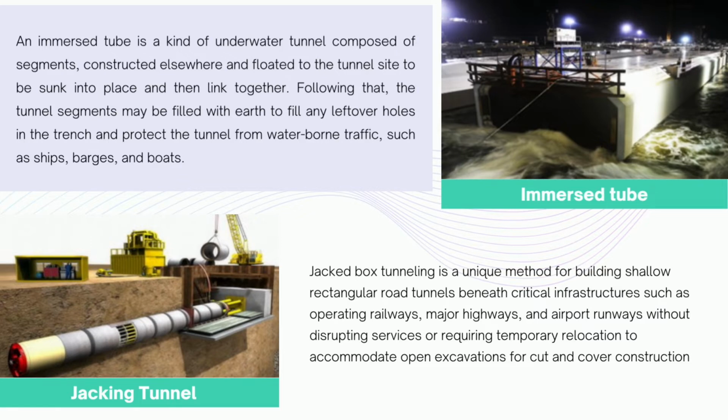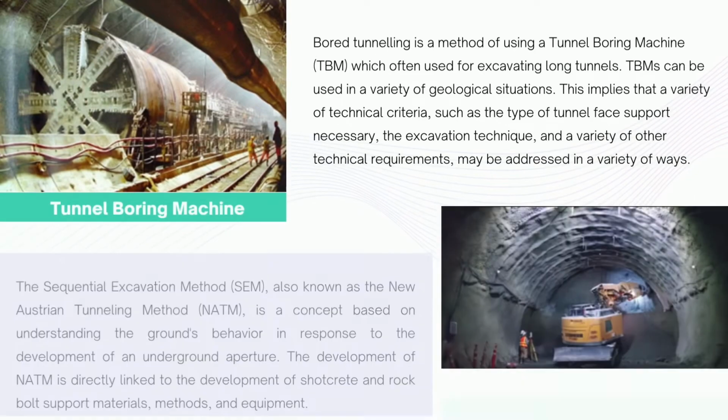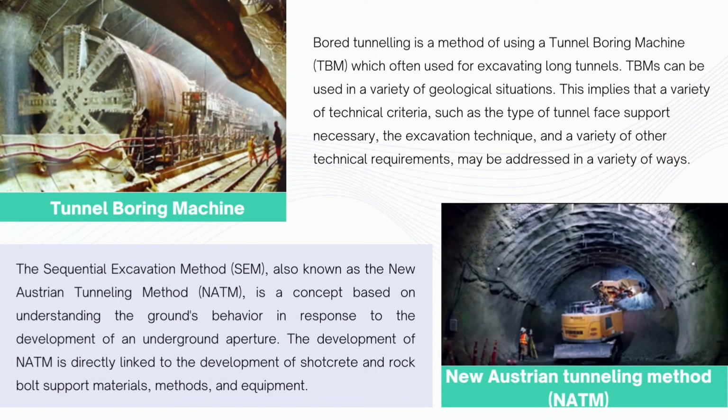Jack-box tunneling is a unique method for building shallow rectangular road tunnels beneath critical infrastructure. Next, bore tunneling is a method of using a tunnel boring machine, which is often used for excavating long tunnels. Lastly, the sequential excavation method, also known as the New Austrian tunneling method, is a concept based on understanding the ground behavior in response to the development of an underground aperture.